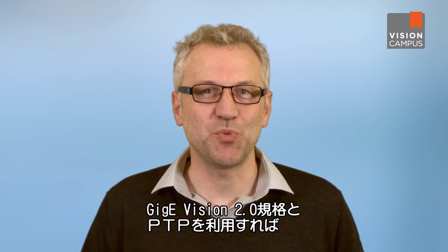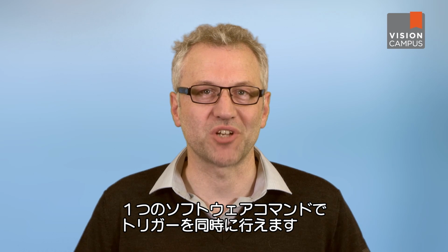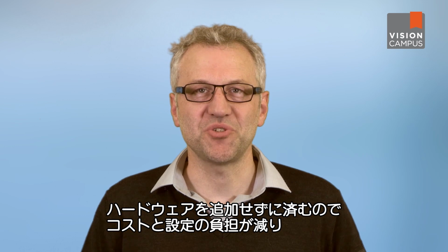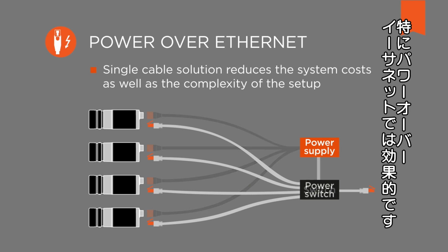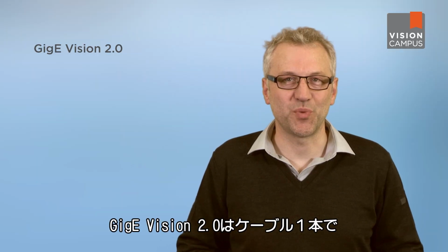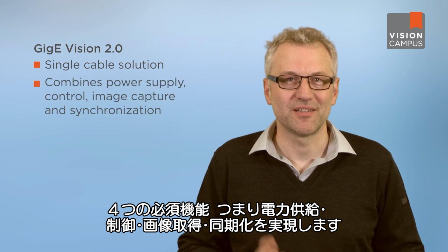Thanks to the GigE Vision 2.0 standard and PTP, multiple cameras within a vision system can be triggered with a single software command synchronously. You don't need an additional hardware trigger. This reduces the system costs as well as the complexity of the setup, especially with cameras using power over Ethernet. With GigE Vision 2.0, you can use a single cable solution as it combines 4 essential functions, namely power supply, control, image capture and synchronization.